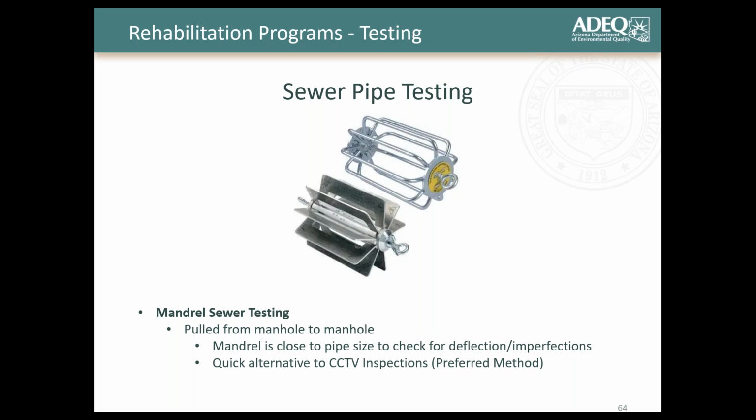So usually, if you have an 8-inch pipe, you may use a mandrel that's designed for 8-inch, but it's usually really 7.5 inches. And some of the designs, like the one you see up top, are a little bit collapsible, so if it starts getting stuck, you'll feel the snugness, but you'll still be able to pull it out. Not every mandrel is like that, and some folks don't like that. Some people prefer a more rigid design to really test your sewer line and make sure that if this 8-inch mandrel does not fit through this segment of line, then we're not right.